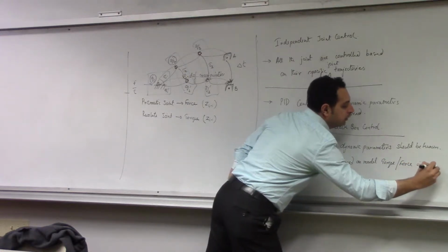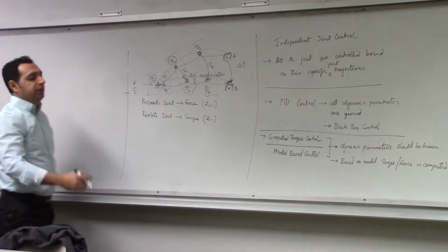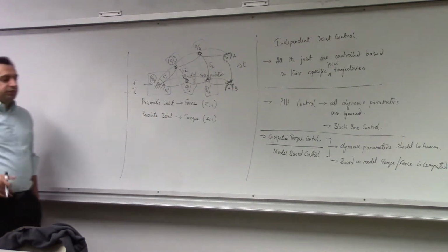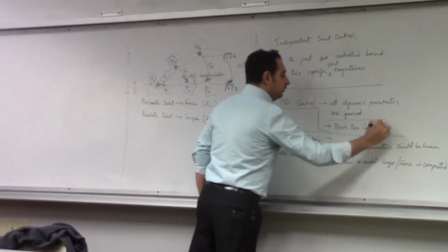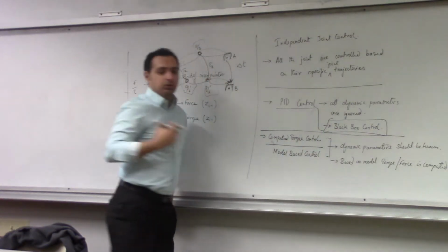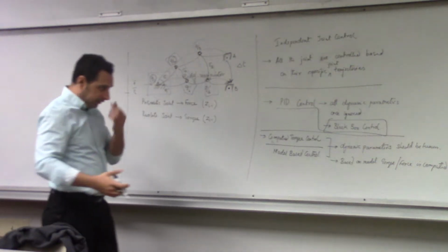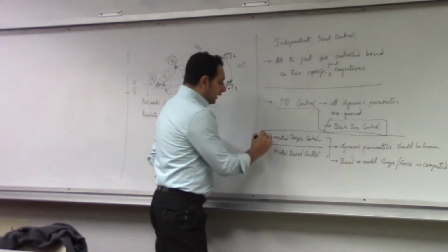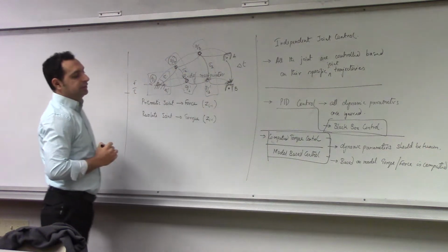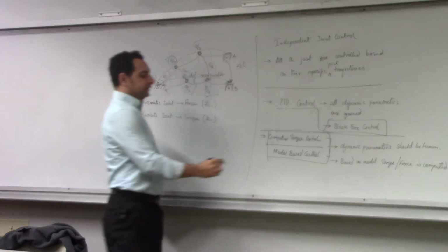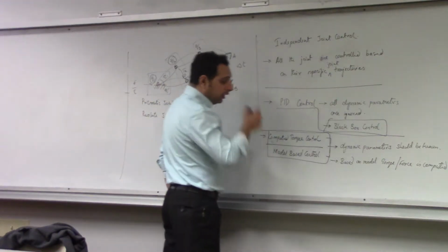So we'll briefly go over these two control strategies. One is PID control or black box control, which basically does not require you to know the parameters. It's just like moving something, what we do in everyday life. And computed torque control is a very calculated or very precise control method, because in this case you take into consideration all the dynamic parameters of the robot.